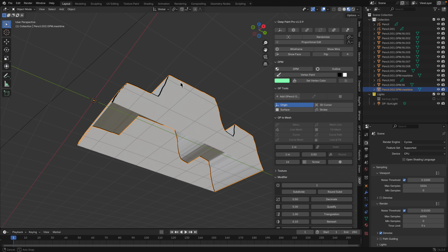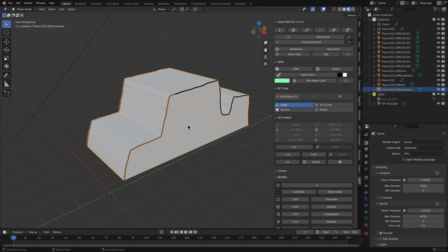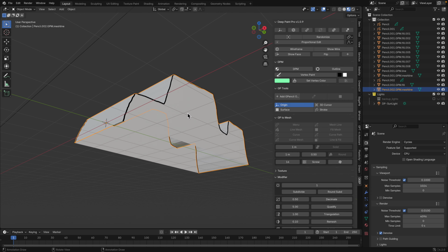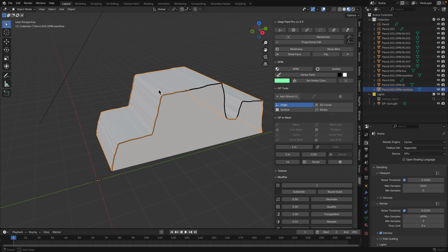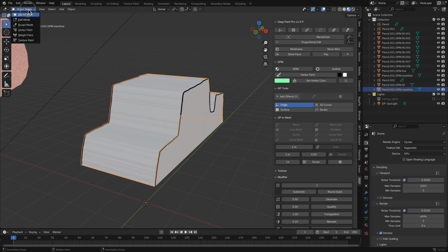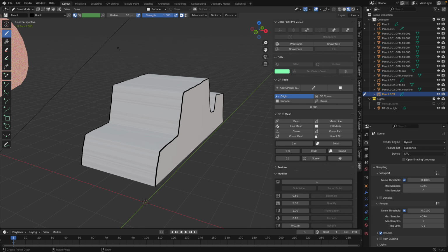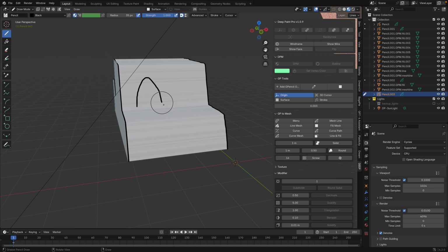If this is already extruded objects, you can turn it into solid and then you can paint on it. Yeah, it's the basic stuff, but if you are doing like a 3D doodle, this is one way to do it. E, create blank grease pencil, and then just set it to surface, and yeah, you can draw things.